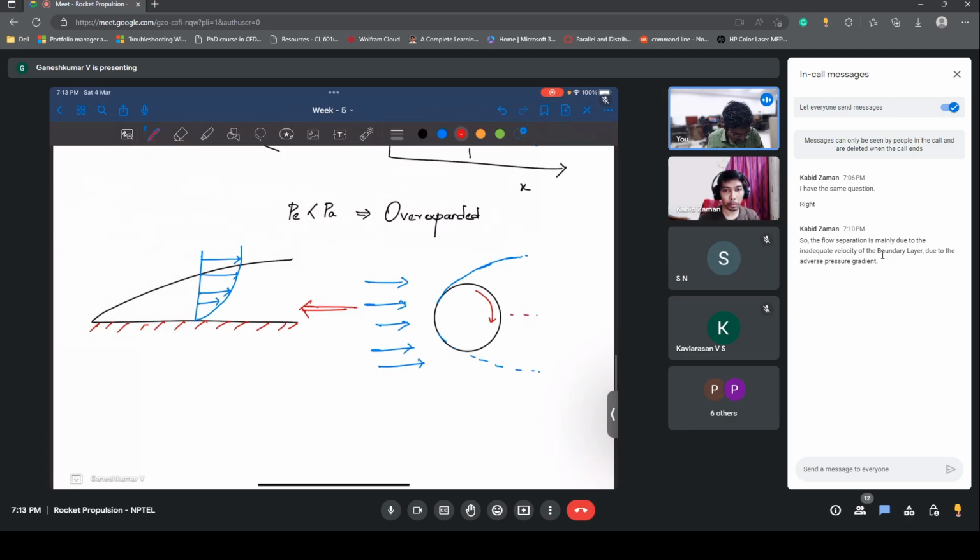The pressure here is going to be high, right? The flow is happening this side, but the pressure gradient tells that flow should happen the other side. This is the adverse pressure gradient due to the form of the sphere, right? So at somewhere downstream, the boundary layer is going to separate, the flow is going to separate from the ball.